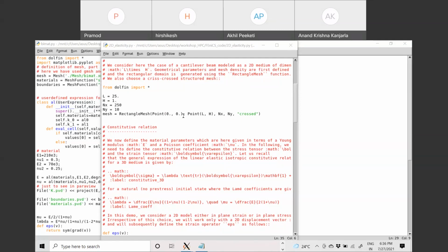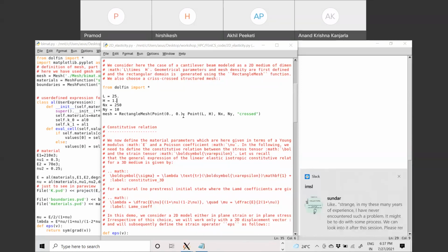In the 2D case, the displacement in x direction and y direction, and in the 3D case displacement in all the 3 directions. So how the code looks is shown in 2D_elasticity.py, right? You probably want to run the case and see in ParaView, and you select ux, uy, and uz, and you might be able to see the displacement. Okay.